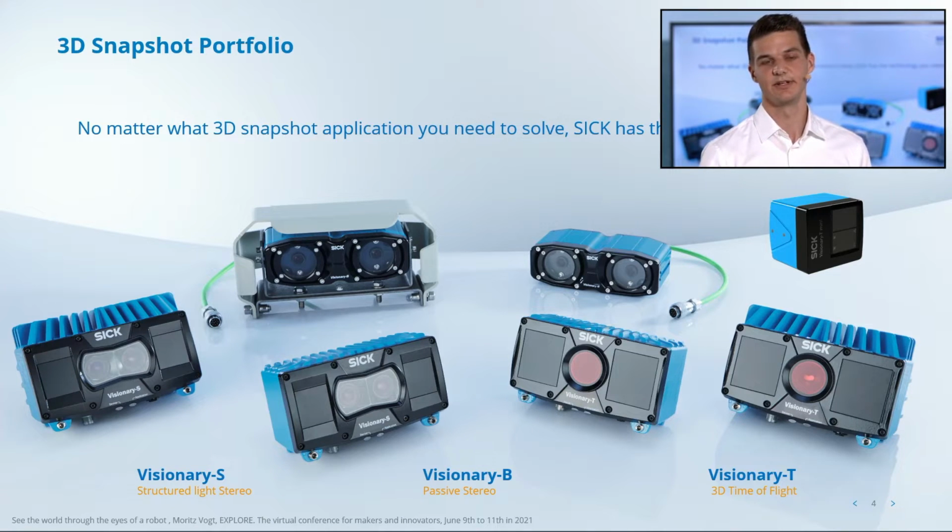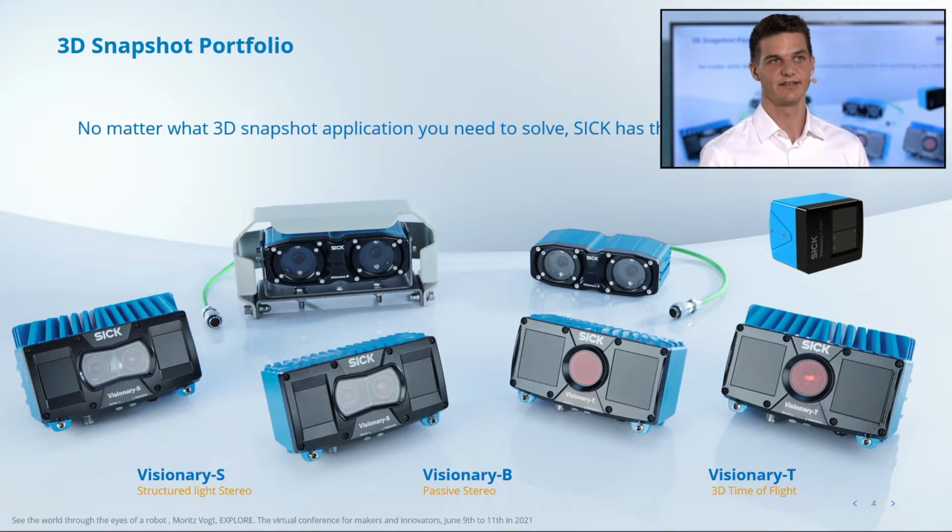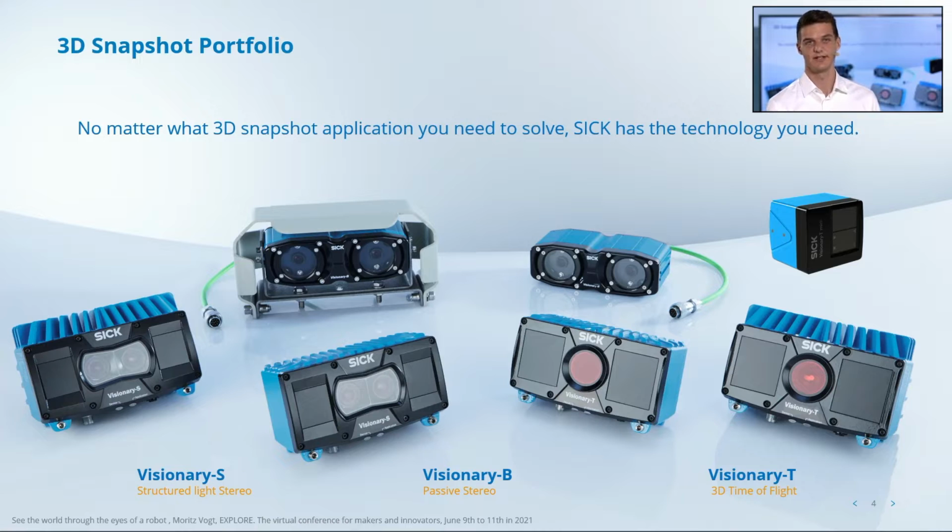So we are using the time-of-flight technology, the stereo technology, but also the combination of structured light and stereo technology to acquire 3D data. And snapshot in this case means that all of the devices do not need any kind of movement of the sensor itself or any kind of internal moving parts inside the sensor. So we really take the image with one shot, and this can happen at a high frame rate.